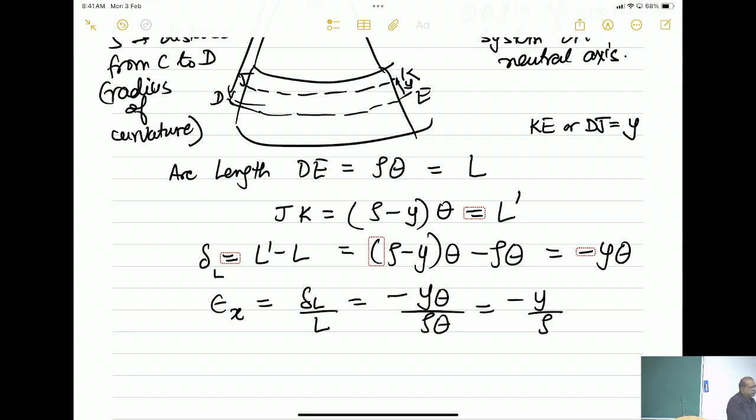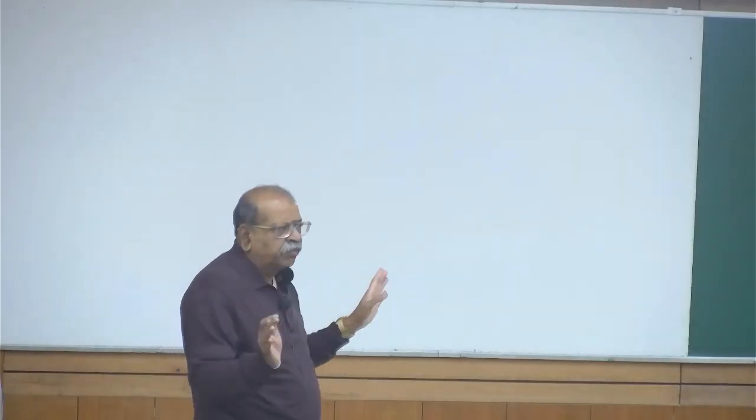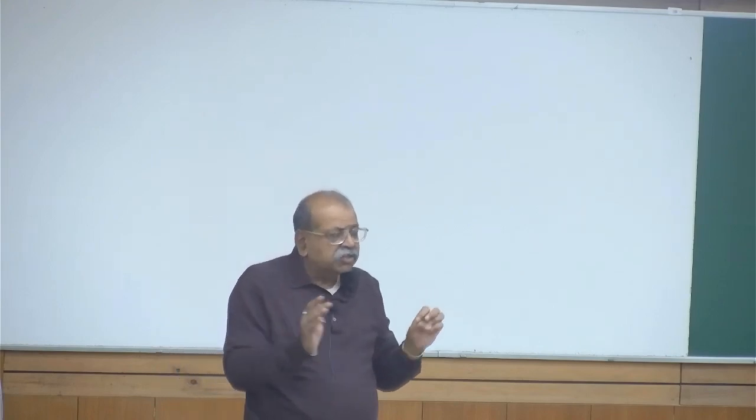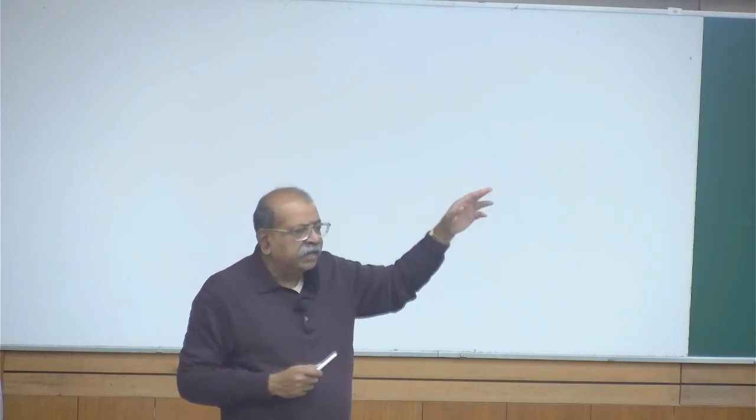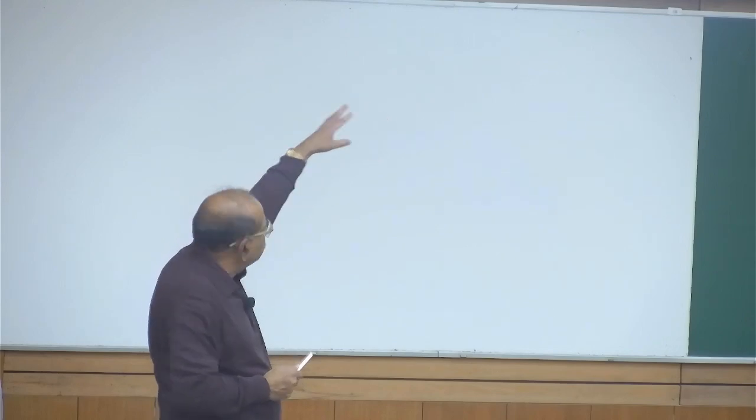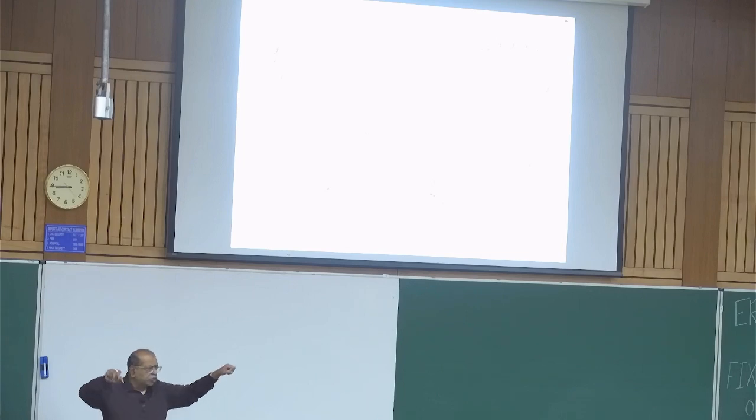Just see this. So far, this is all geometry. Stress-strain relations were used just to show that some of the stresses were zero, and at one stage I said this is equal to stress, but otherwise all this argument is geometry based, so it will not depend on the material of the bar, as long as M is uniform. Of course, the area of cross section has been assumed to be constant. So this is what we have for strain.